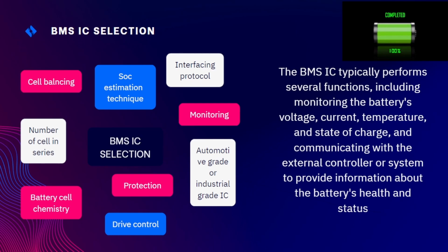Next one, open wire conditions. These are disconnected or poorly connected wires which can cause errors with the BMS. Identification of faulty wiring can prevent issues with the safety and performance of the system. Next one, overcurrent or short circuit conditions can cause over temperature conditions that can lead to fire. Over temperature conditions can signal a catastrophic event in the system, and the BMS needs to take appropriate actions to implement cooling or shut down the battery.